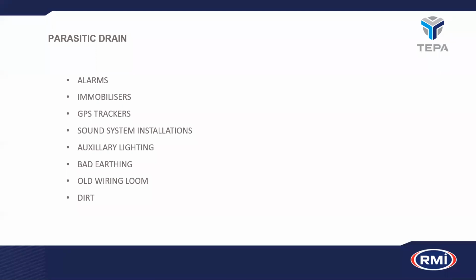However, we've had many, many instances where a vehicle's battery is being blamed, is being regarded as rubbish, it doesn't last, it fails, but the parasitic drain from the immobilizer has reached a point where it's drawing on the battery so hard that it's actually flattening the battery overnight. And the next morning, the battery's flat, battery gets the blame, but in fact, the immobilizer is actually doing the damage. And the vehicle gets jump-started, gets driven for the day. Overnight, the battery's flat again.